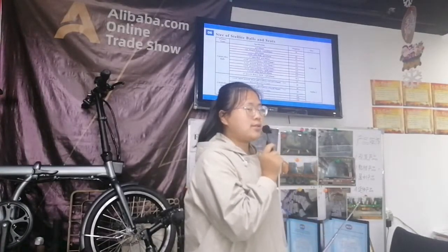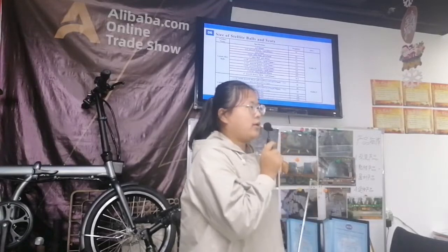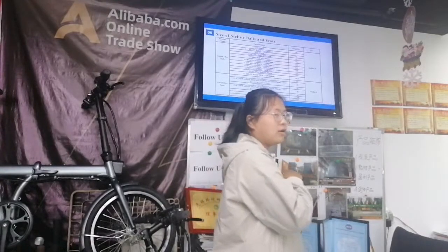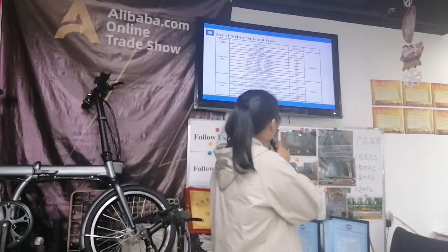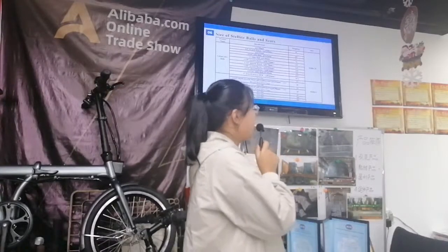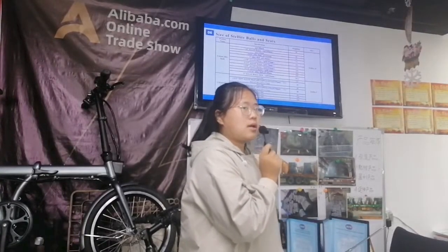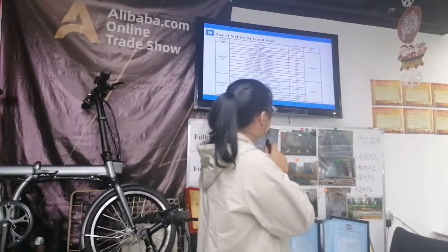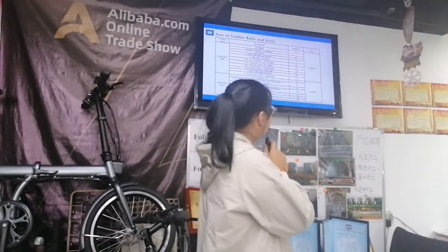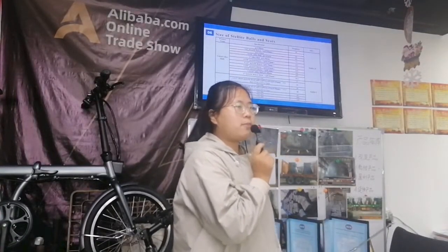Next, cobalt alloy seats. The standard is API standard. For example, C11 to 125. The size of bore is diameter 19.05 millimeter, and the size of the seat is diameter 23.32 millimeter. Inner diameter is 13.97 millimeter, and the height is 5.7 millimeter.